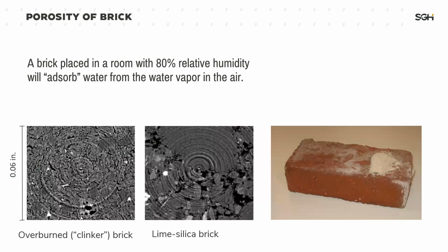A quick note on the porosity of brick. If you put a brick into a bucket of water, it will absorb water, and that's called absorption. But if you leave a brick in a humid room, say 80% relative humidity, it will adsorb water from the air. It has these pores that, if it's dry, will be empty. And if you leave the brick in a humid room, then those pores will get full of water from the humidity in the air.